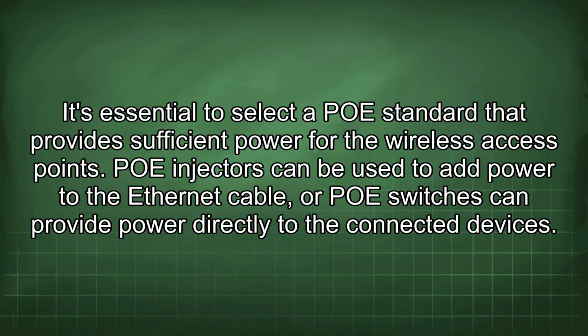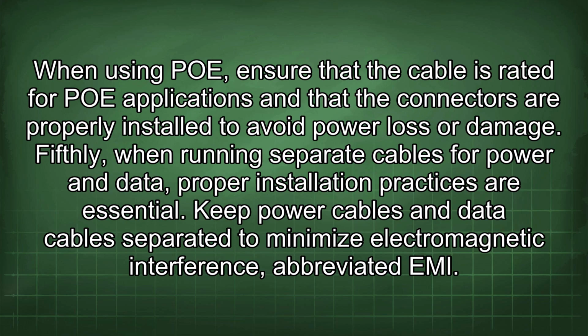PoE injectors can be used to add power to the Ethernet cable, or PoE switches can provide power directly to the connected devices. When using PoE, ensure that the cable is rated for PoE applications and that the connectors are properly installed to avoid power loss or damage.